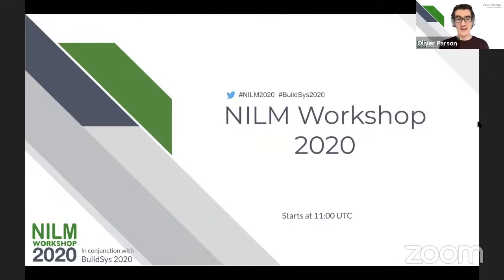I should probably start with just a brief definition of NILM, so talk about what the topic is and why we're here. So NILM stands for non-intrusive load monitoring, and this is really the problem of separating a building's energy consumption into individual loads. Now, this is also known as energy disaggregation, and really the non-intrusive component refers to the use of a single point of measurement and software or algorithms to separate this energy consumption into individual loads or appliances. And this is in contrast to intrusive load monitoring, where you might install one monitor per load or appliance within the home. But we're really talking about this non-intrusive case where you use a single piece of hardware installed at a single point of measurement.